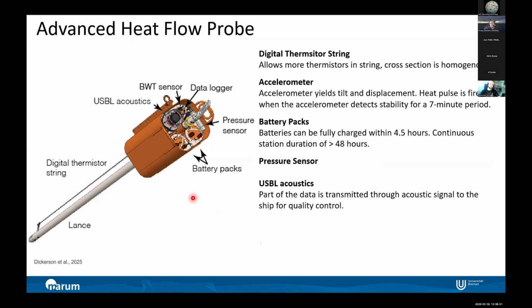so you can very quickly access the quality of your measurement. You can see how the probe is situated in the sediment, if it's vertical or if the probe fell over and did not penetrate. You can also very quickly see how deep the probe penetrated within the sediment. And then you can decide if you want to retrieve the probe, or wire a little bit more in, and then move to another position to make a new measurement.